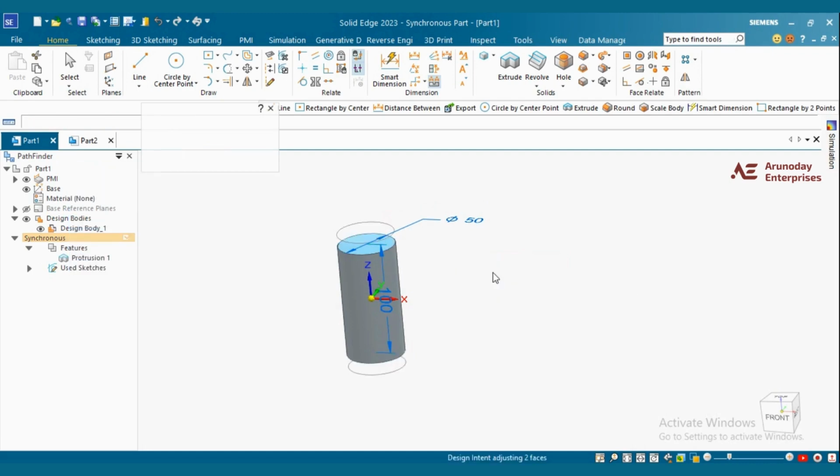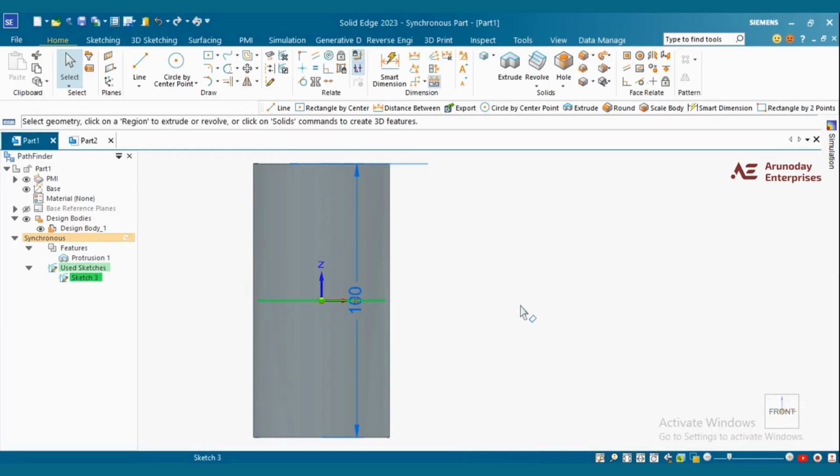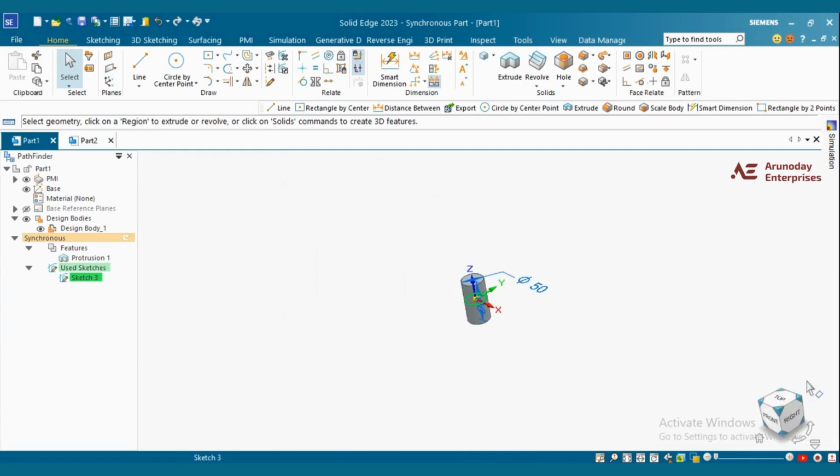For the middle one, if you click on that, we can see that there are both arrows over here. Whenever we change the dimensions, it will change symmetrically when we keep this option on the center point of symmetric approach. So it will require less time to do the modifications because it does not depend upon the history that is created on the left hand side.